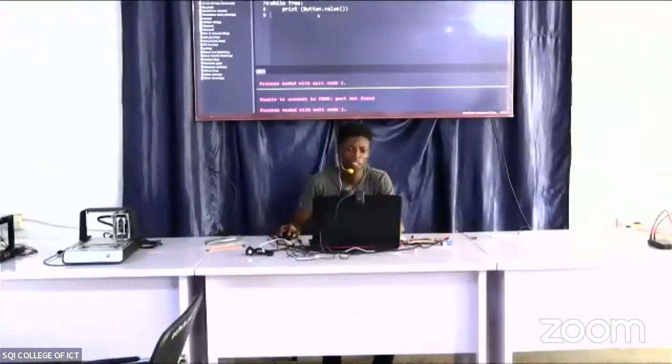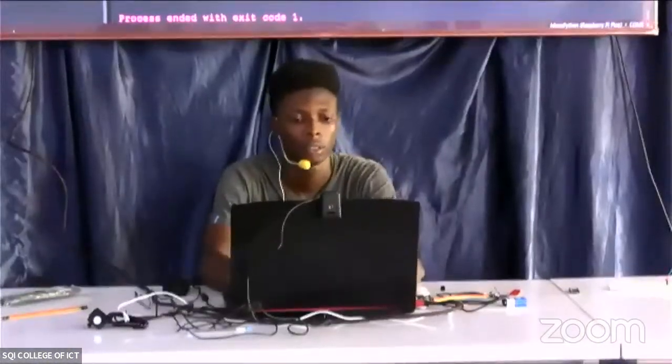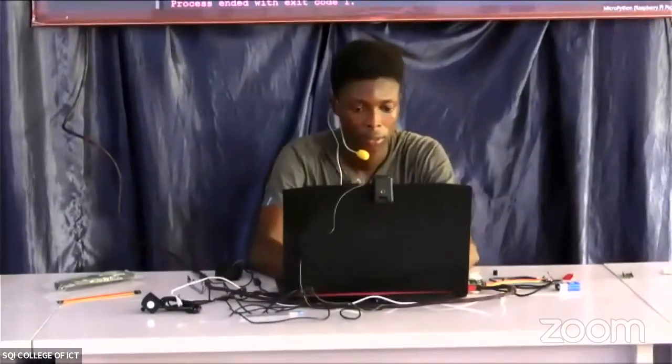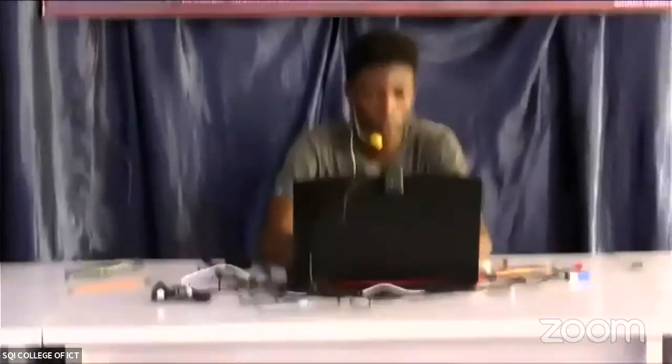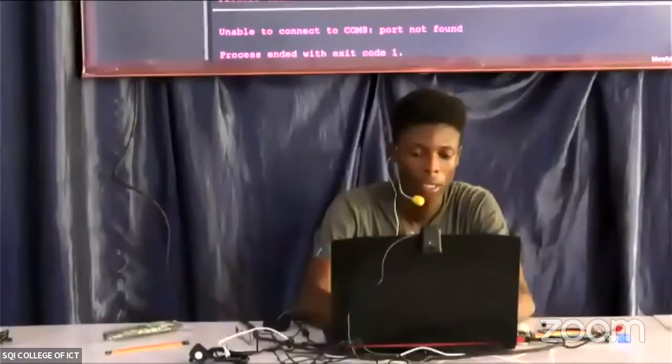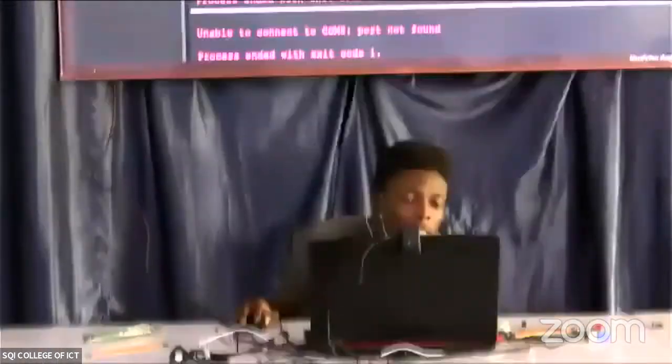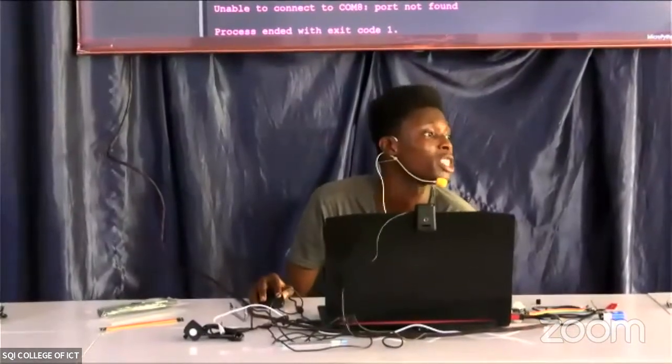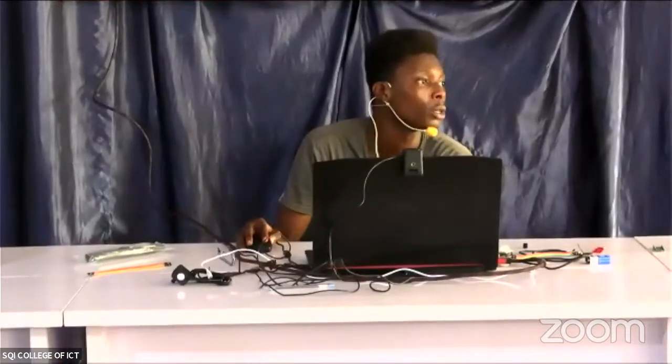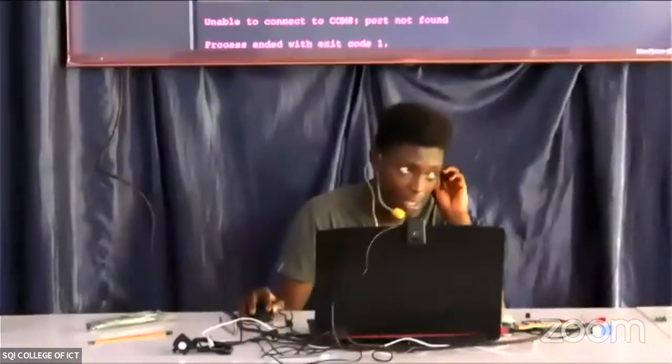All right. Introduce a delay to your code, please. Time dot sleep. All right, press the button. You should have a switch of state between 0 and 1. If you press the button, you should have 0. Introduce a delay first.